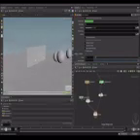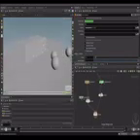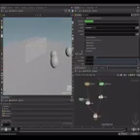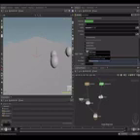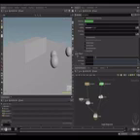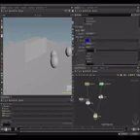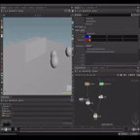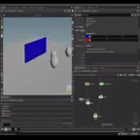We're not gonna use a volume representation to set this static object. So if I turn off display geometry, this will be deleted. So I need to go to the collision tab, bullet data, and show guide geometry.